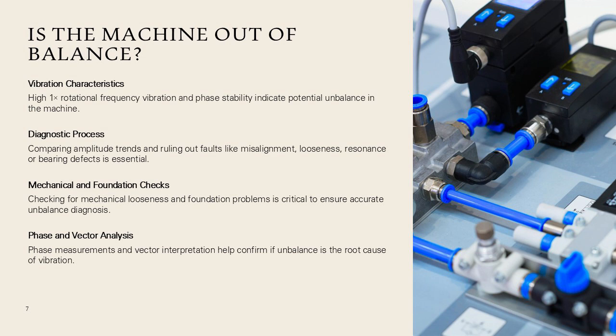Key indicators include high 1 times rotational frequency vibration, phase stability, minimal axial contribution, and similarity in waveform shape across radial directions. The diagnostic process involves comparing amplitude trends, confirming that other faults such as misalignment, looseness, resonance, or bearing defects are not the primary contributors.